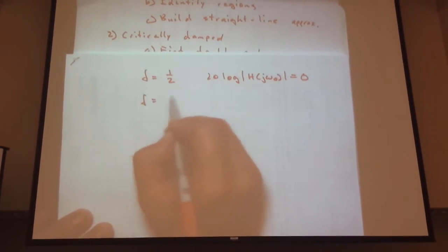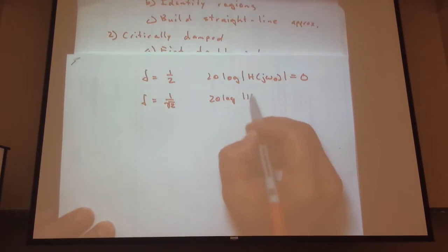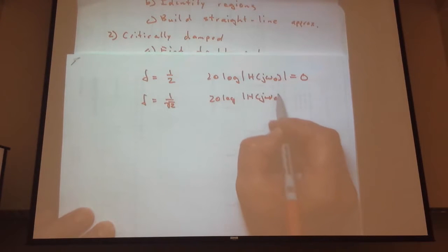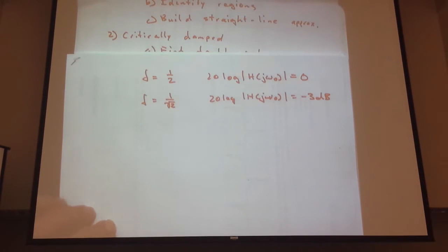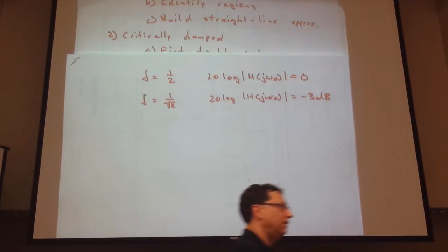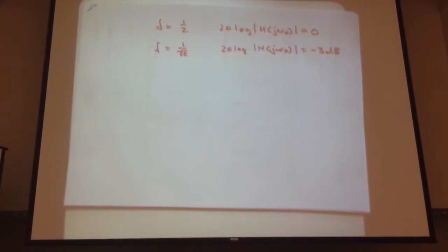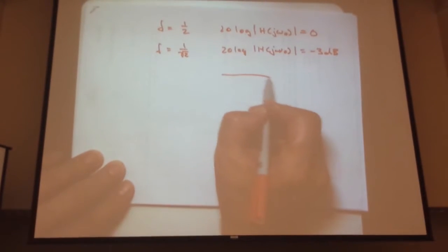And just for our other item of interest, and the classic value, -3 dB. So that brings us into the 3 dB variation I talked about, where the passband is a variation of 3 dB with a little bit of hand waving. That's a convention that's been kind of agreed upon, not an absolute condition, but this gives us a passband.